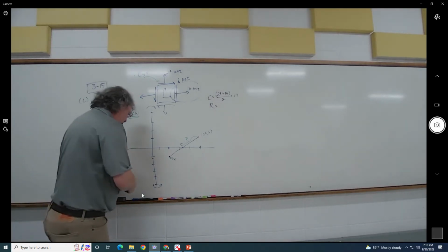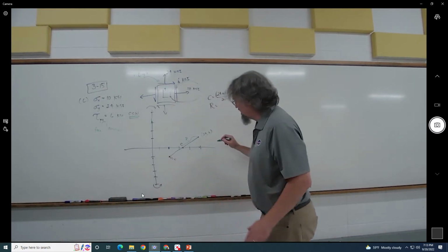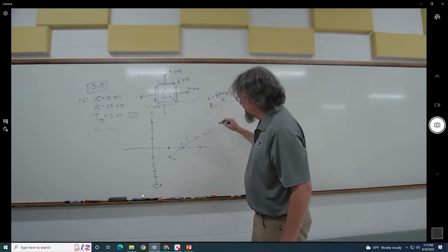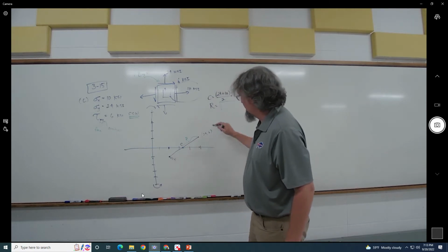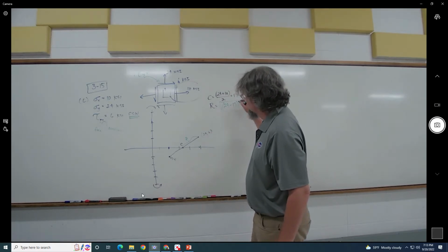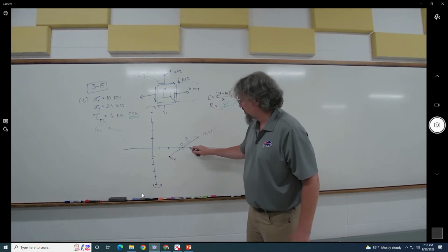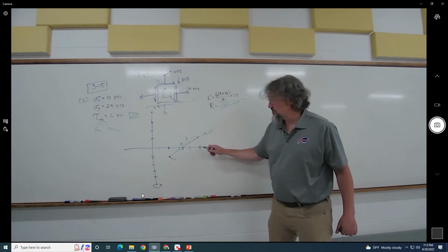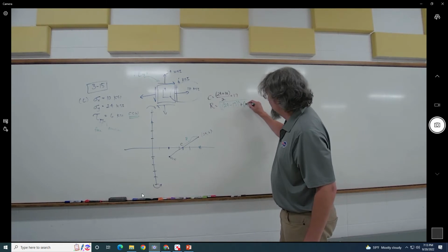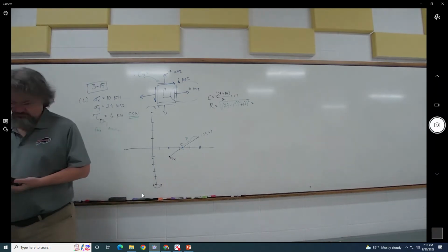The radius, like I said, is sometimes a trickier thing for people, so I try to communicate as best I can. We're just trying to figure out what these legs are, right? So we're taking the square root, and the horizontal leg is going to be my 24 minus my 17. Because I know that's 17, and I know that's 24, so I want the horizontal distance right there, squared. And then I also want the vertical distance, which is just going to be my shear stress. And we probably need to use a calculator for that.